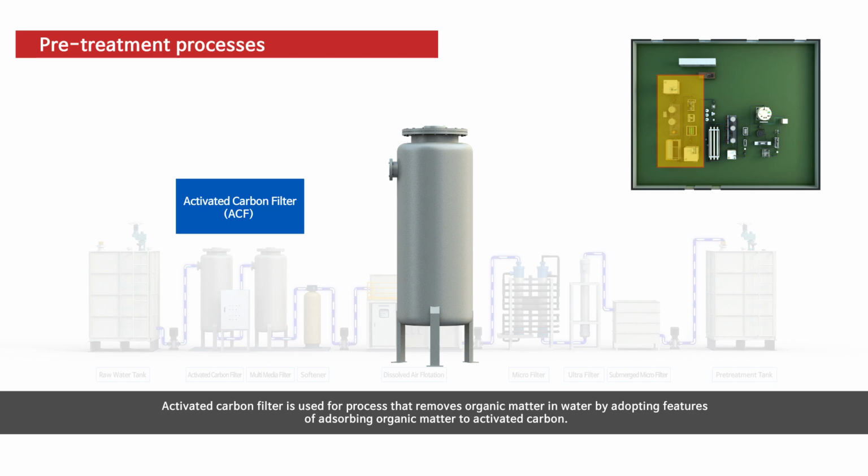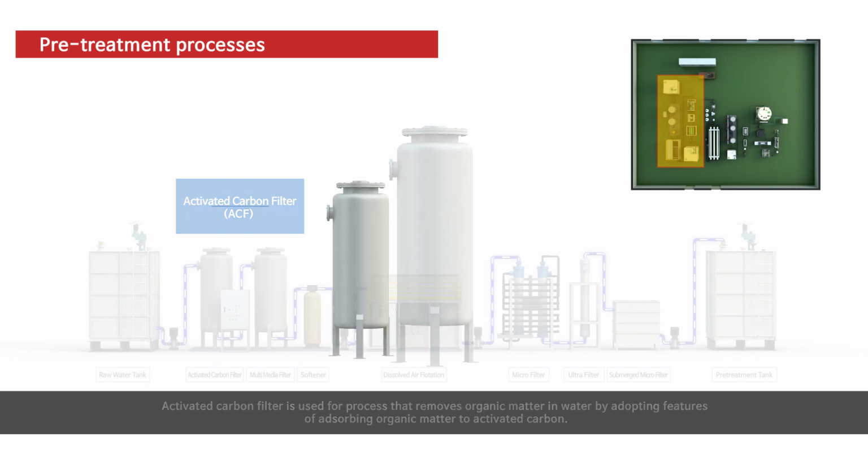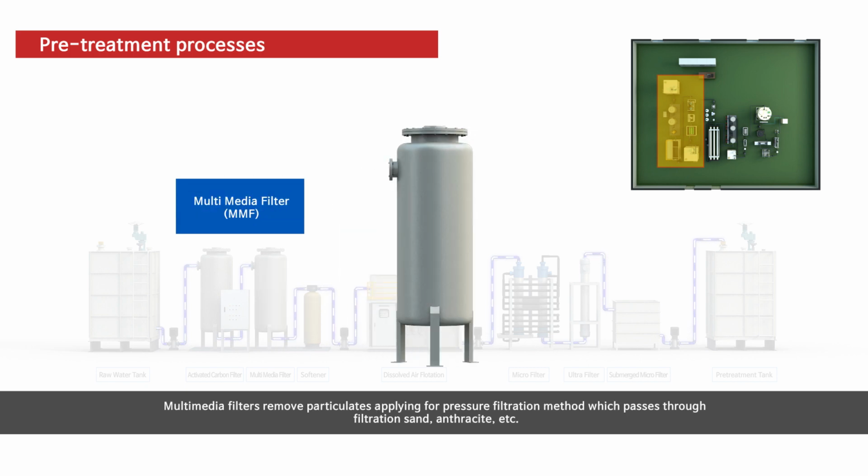Activated carbon filter has a removal process of organic matter in water, applying the adsorption principle between carbon granules in columns and organic matter. Multimedia filter has a detention process of particulates passing through filtration sand, anthracite, carbon, etc. using a pressure filtration method.